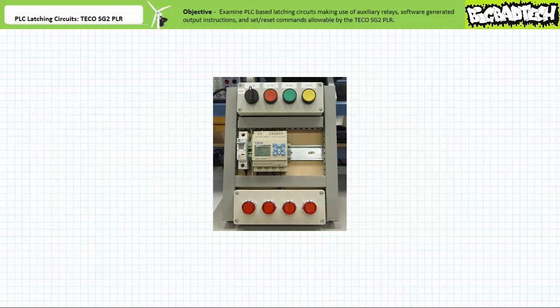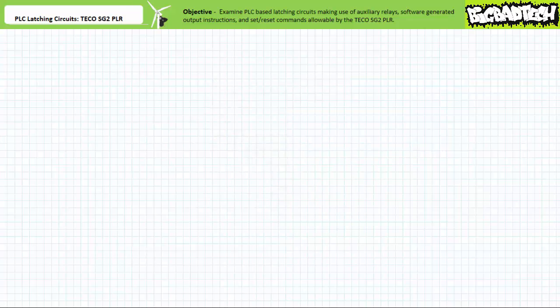When the system is placed into operation, note that when an operator presses and releases the normally open green push button on input 3, the first pilot light turns on and stays on as we'd expect. When an operator presses and releases the normally closed red push button on input 2, the holding circuit is broken and the first pilot light turns off and stays off as we'd expect. Outwardly, the behavior of this program is identical to our two previous implementations, only the program is ever so slightly easier to read.